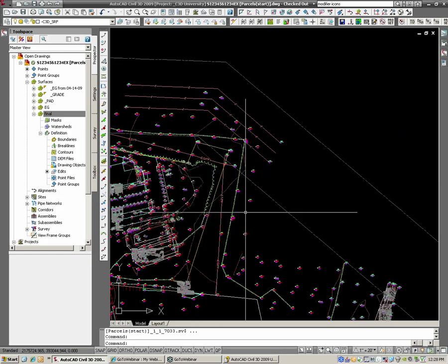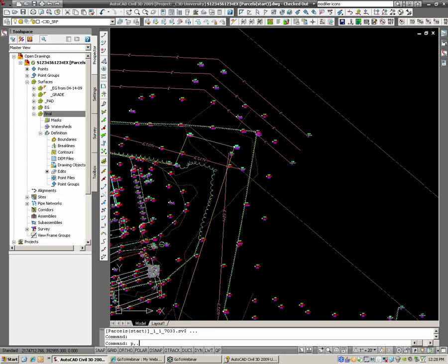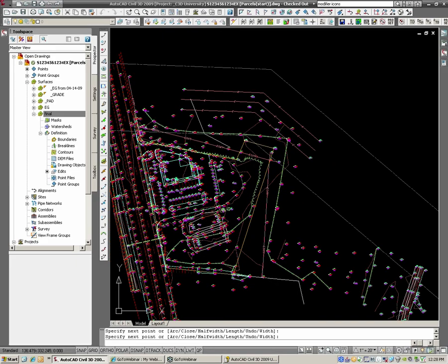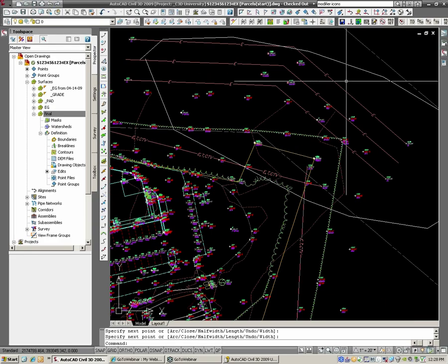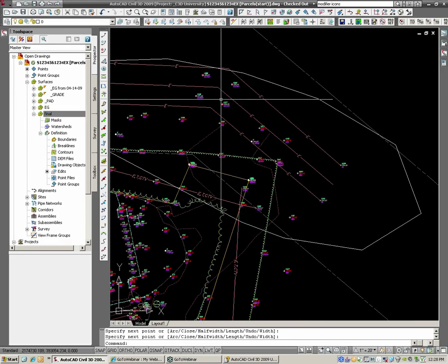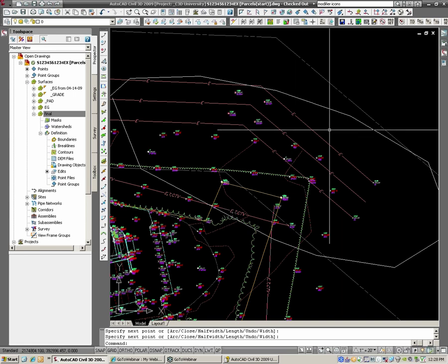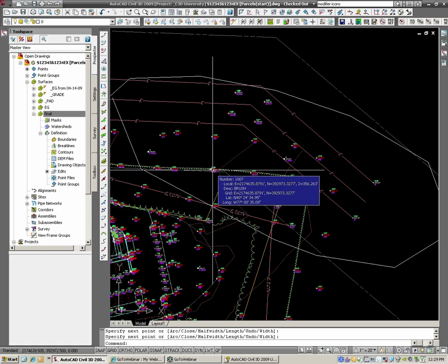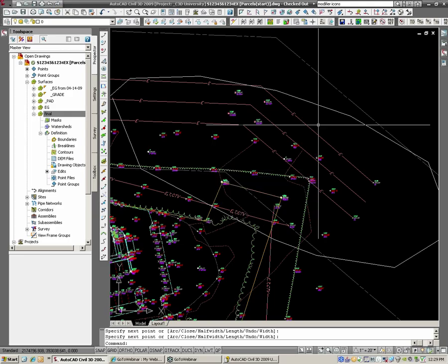So this is really, really useful when you have a survey of a certain area, and then the contractor builds a berm maybe right here. And you can see there's overlap. Well, you could make a surface for your new berm that you went out and surveyed on a later date and paste it into your overall, and it will trump the triangulation in there. But you still have both. So if you take out the paste, it will come back. If you change the order, the existing grades can trump the pad if you'd like.